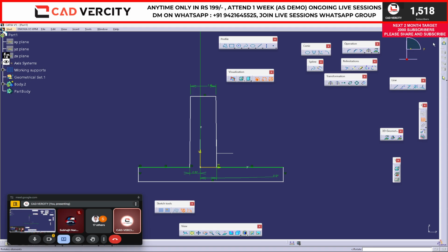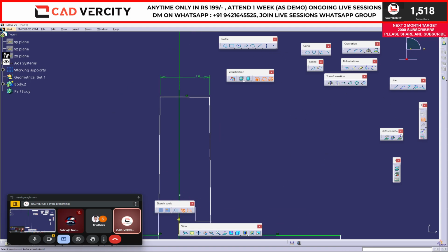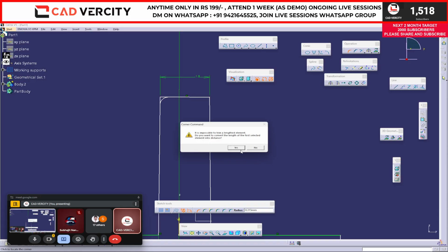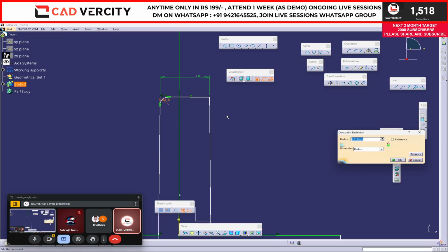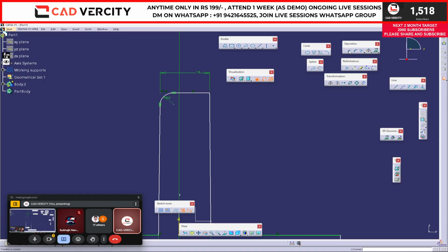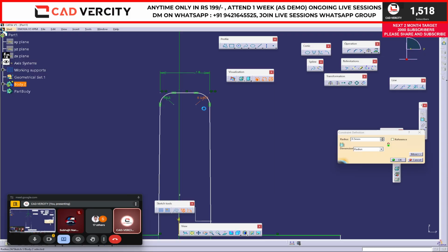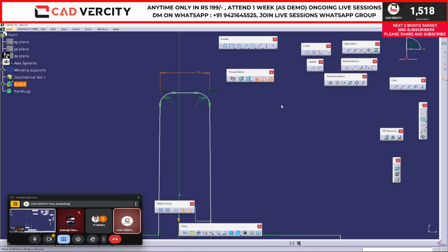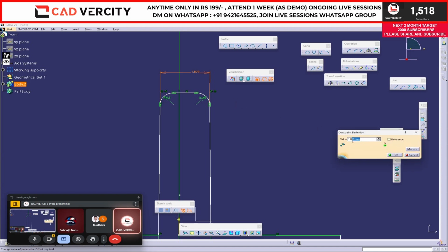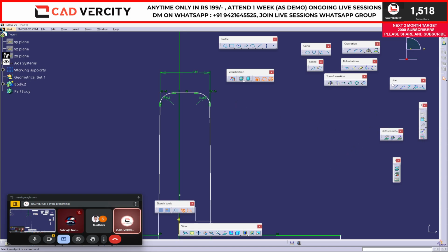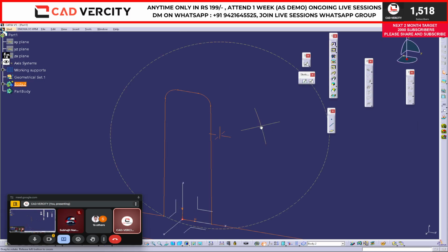Okay, now shall I apply corners as well? Yes, sir. Let's apply corners on this side. Let's apply a corner of 0.5, enter. Corner on this side. Actually, we don't apply corners in sketches, but for now, just for your explanation. Okay, delete this one, constraint. Sir, I am changing the anchor point also. Same is fine. So you have 1.81, I think. Okay, exit, pad.